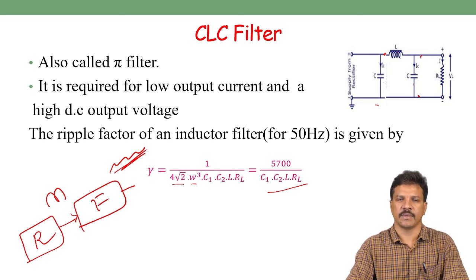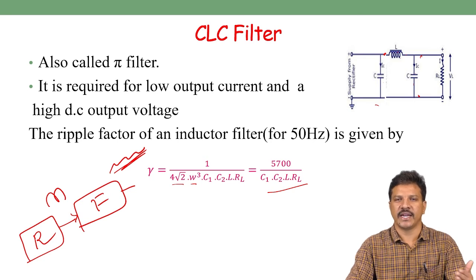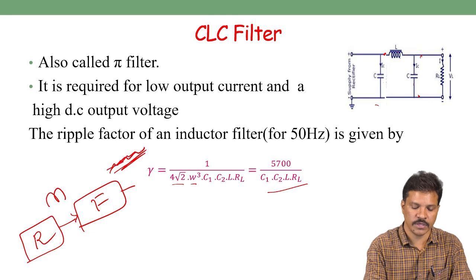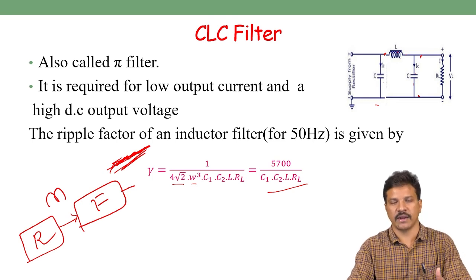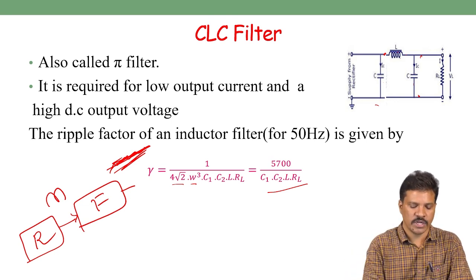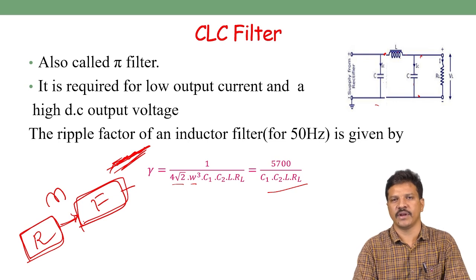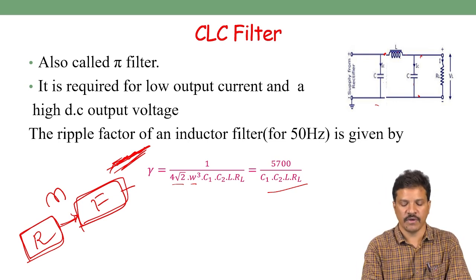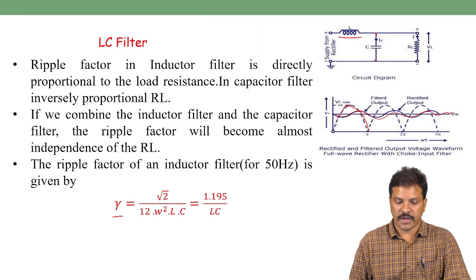In the regulator, sometimes old basic regulators like a Zener diode are connected across this filter, and then it will smooth this AC component to a constant DC component. With advanced circuits, regulator ICs, we can pass the filter output through the regulator, smooth it out and get perfect DC at the output. That's why the output of the rectifier is given to the filter, and the filter output still has both AC and DC components. Again when we connect it to the regulator, it will filter out and we will get perfect DC. Okay, so these are the different kinds of filters